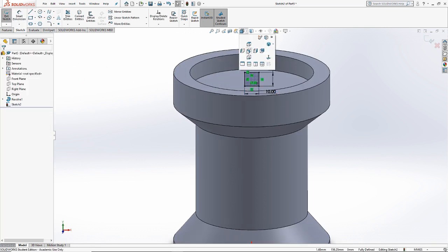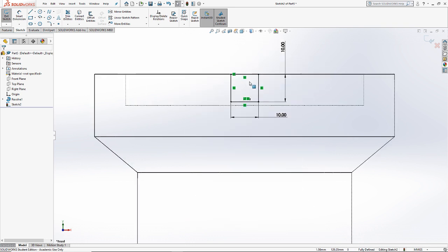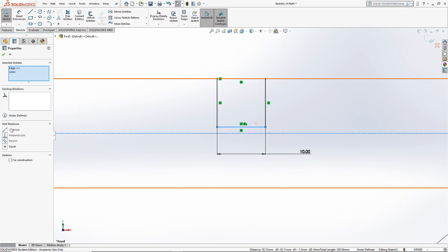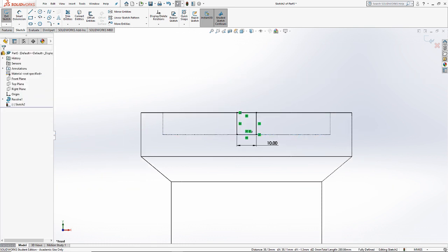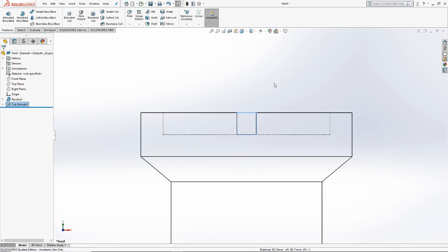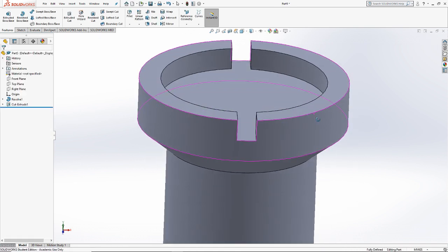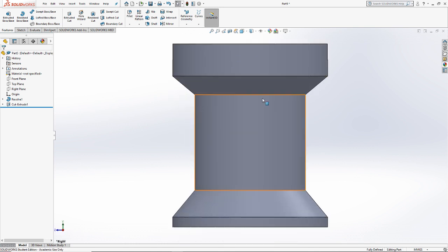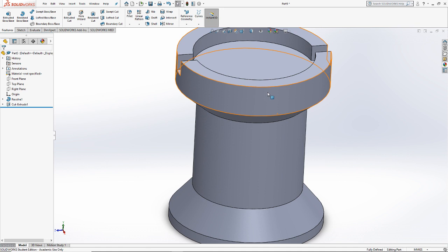Actually, if I wanted to be a little bit more like the homework assignment, I could get rid of this height and just tell it to be collinear with the bottom of that top part of the rook. Now when I extrude in both directions, I have one of the notches. So I could repeat that process on the right plane as well, cutting out to create that shape. That is a way of doing it.